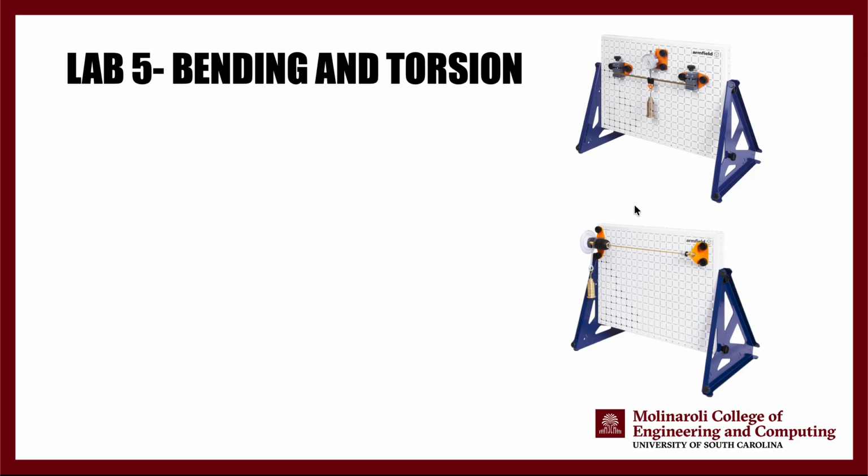And this is our torsion mechanism. We have an arm here that is going to help us apply torque, and a very small device here that is going to help us measure the angle of twist. Keep in mind that this is an analog measurement, meaning the uncertainties are going to be pretty high.